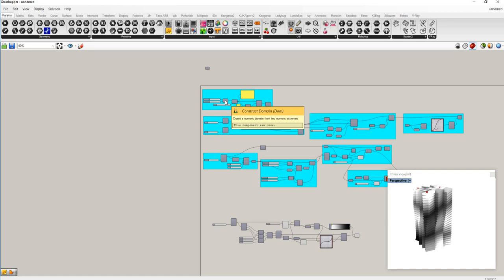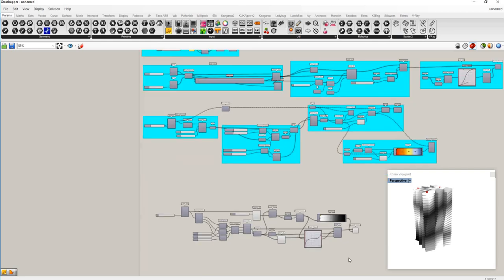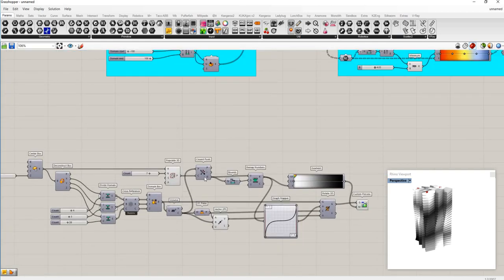And all of those will work to make various types of arrays. And then when you use them for attractor points, you can start to use distances from points. You can use a distance to a line or some other geometry, and that can affect the attractor point rotation or translation or scaling. You can do that as well.